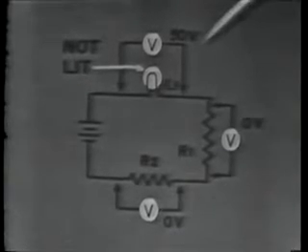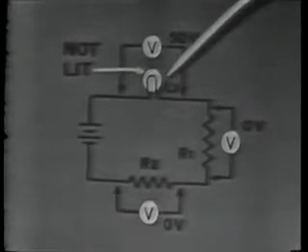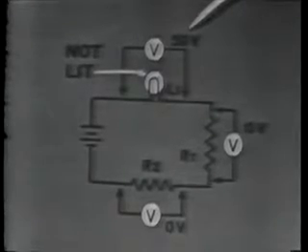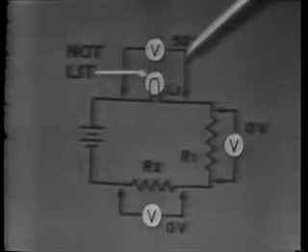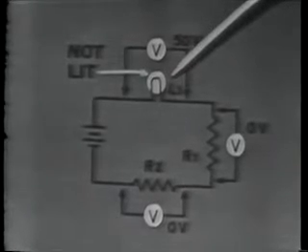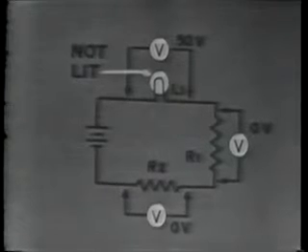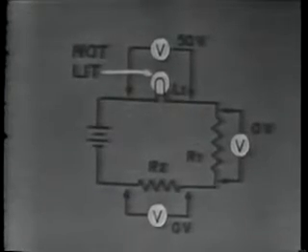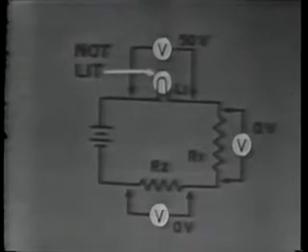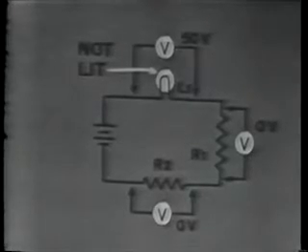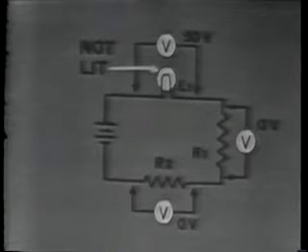So this boils our trouble down to the lamp. Having 50 volts across it and yet not being lit, L1 has to be open. So, with the voltmeter readings as indicated, L1 is open, and R1 and R2 are neither open nor shorted.